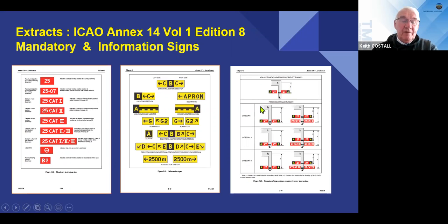So for safety reasons, we move our runway holding position further away from the runway center line, so we have more clearance in those lower visibility conditions. And therefore, we identify those locations. The distance we move from a 75 meter minimum distance for Cat 1 is 90 meters.